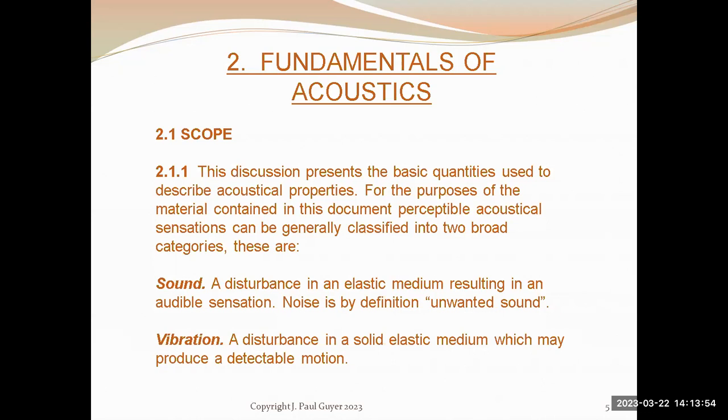So as an example, a fan room in a building, common situation. The source room, the mechanical room needs to be constructed in such a way and using appropriate materials and construction designs to isolate the sound or at least reduce it to an acceptable level so it doesn't disturb the occupants of the building who are outside of the mechanical room. But then there's also vibrations.